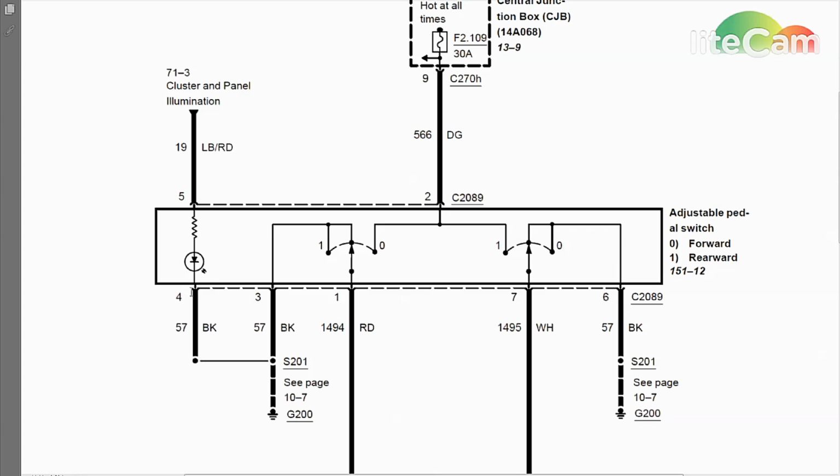And we can go over to here, pin 4, pin 3, and pin 6 on that same connector. You can see all colors right here, black, black, and black, because it's all the ground. And make sure that we are able to run a motor or turn on a load with these circuits also. What that does, it tests the integrity of the circuit for load carrying capability and amperage.